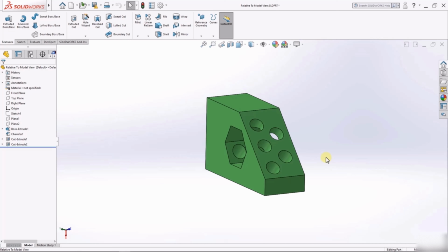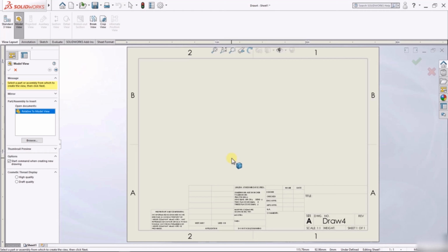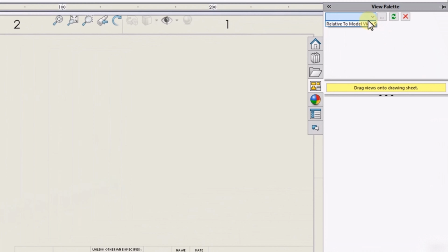We will start by opening a drawing file. So I'll go to new and then select drawings. And then I'll select the first standard 4 pages and then OK. Now I'll simply try to insert the normal or default views. So I'll go to my views, select the model.